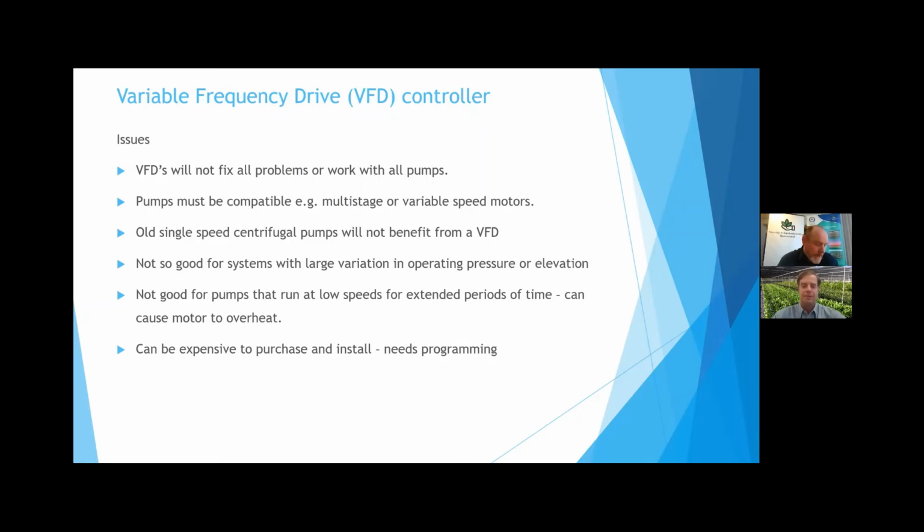So true. You can also buy something along the lines of a VFD for other motors. In the case of greenhouse climate controls, where they're automated and you have motors that open and close vents, you can get small motor controllers that do a very similar sort of thing. They monitor the power going into that motor and adjust the power according to the amount of torque or stress that's being put on that mechanism. And they also save you energy.